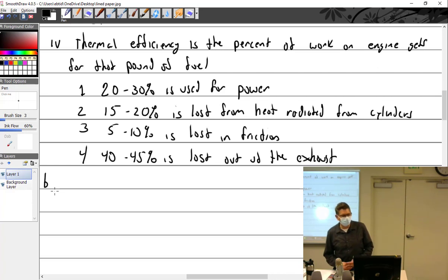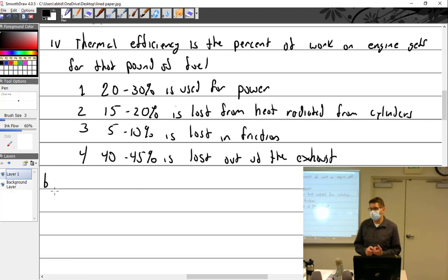One of the guys asked him, where are we with this fuel? And he said, you don't really think about, as just a normal person, what it entails. He said, not only do we have to create this fuel, our engines need high octane. Otherwise, they detonate. And that detonation, like I said, is like hitting a piston with a sledgehammer. It can destroy an engine in less than 1 minute. I mean, catastrophic disassembly, failure, falling out of the sky type damage in less than a minute.